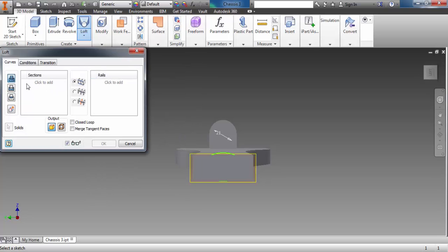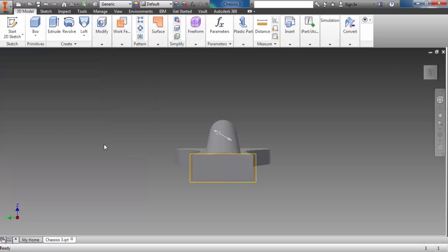And what it's looking for here is 2 profiles that you want to join together. So that's the type of effect it's going to get. So the first profile that we want to choose is this one at the back. There we are, edges, click to add, and the other one is this ellipse here, which just comes forward very quick, and straight away it draws that in, and we'll simply click on that to say okay. We can see there now.